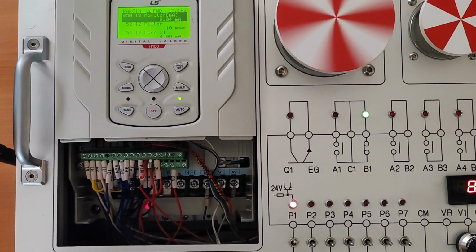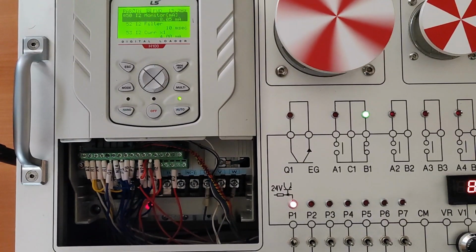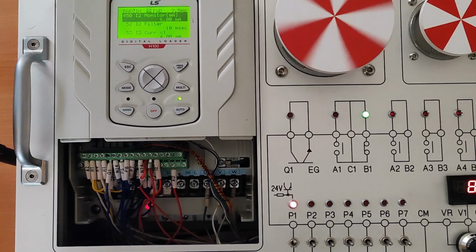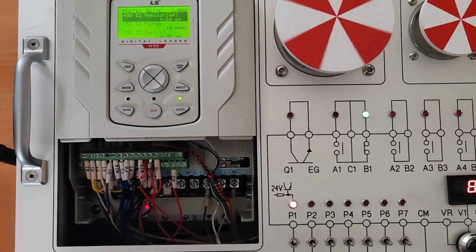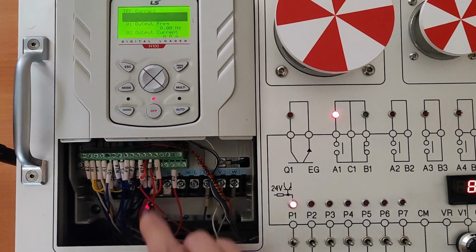Now if I monitor my analog current input signal, if the measured value of this signal drops below the threshold of 4 milliamps, the inverter automatically detects a loss of command error and immediately cuts off the power to the output for safety. I gradually lower the analog input signal, and as soon as it drops below the 4 milliamp threshold, the inverter immediately triggers a speed loss command error message and completely cuts off the power output. It waits for 3 seconds, and after 3 seconds it triggers the loss error.